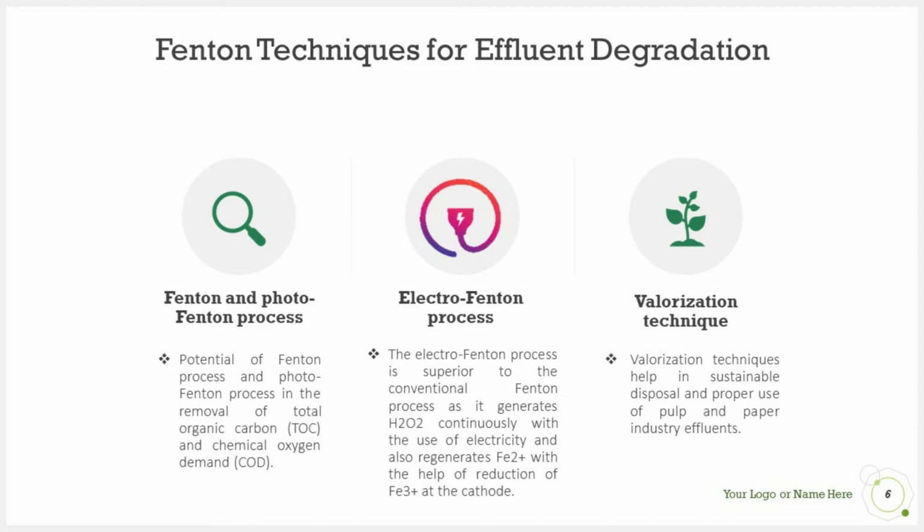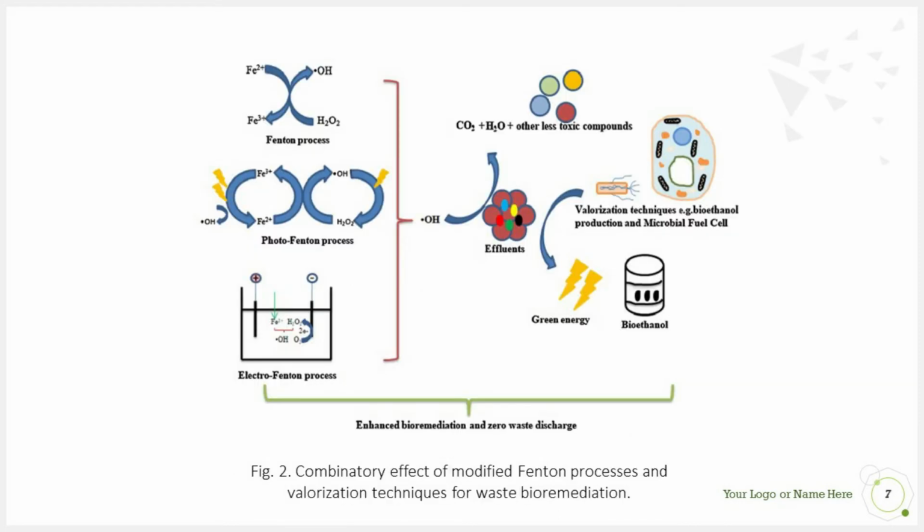The Fenton process can reduce the chemical oxygen demand of biologically pretreated wastewater. Various kinetic models applied for verification indicate that this degradation occurs in two steps. First, rapidly, in which aromatic constituents are converted into acids. Acids are then degraded slowly in the second step.